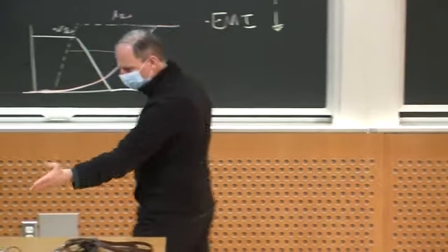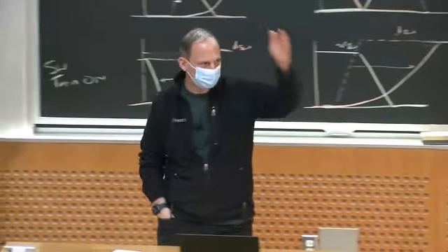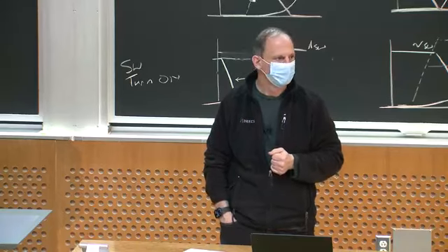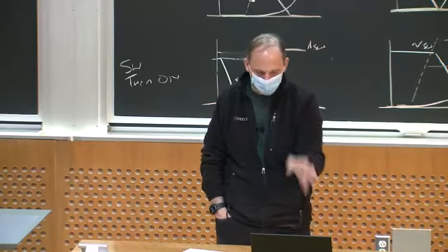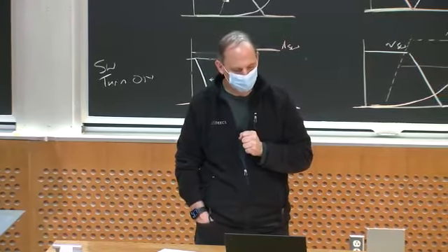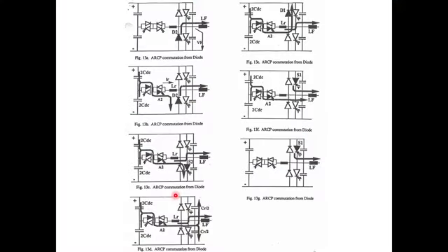This is much more complicated, but on the other hand, it lets you PWM any way you want. And they were running motors with this, and they were running all kinds of special motor controls. So this is a really good circuit for this kind of application. And the things you get are reduced switching loss in the main devices for a small extra auxiliary circuit, which is also soft switched.